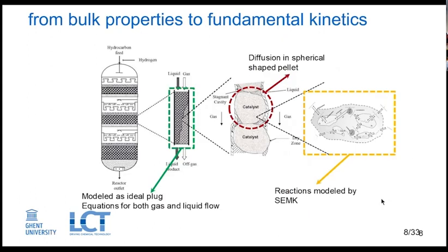Well, a bit about PRIME. PRIME implements for the commercial case a plug flow reactor that considers both phases, gas and liquid. It's a trickle bed reactor. It takes into account diffusion, assuming spherical shaped pellets, and the reactions are modeled following the single-event microkinetic methodology.